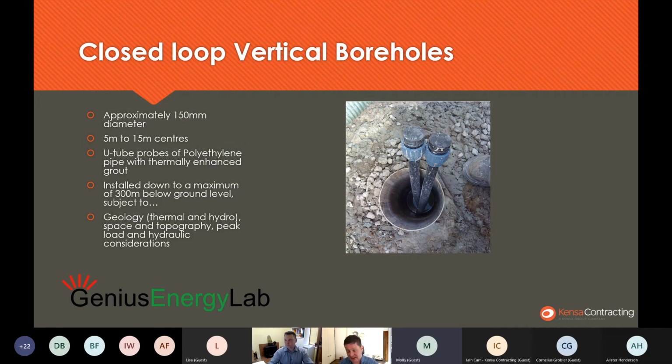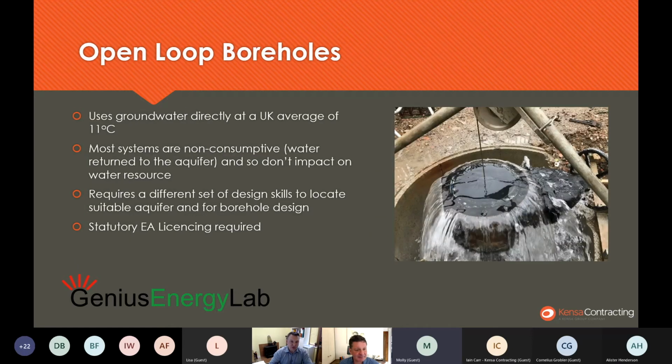So we'll talk in a later session about thermal response tests and conductivity test bores. But a test bore is to confirm our geological assumptions, to work out what the most economic drilling depth is, and then also to physically measure the thermal characteristics of all these different layers in the ground. Quite a complex science, but we are very fortunate in the UK. We've got excellent geological records to work with. However, it's fair to say it's a bit of a detective job to work out what's in the ground. Any questions come in? No, okay. Right.